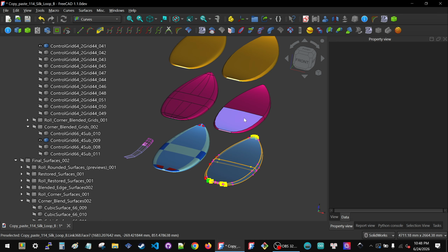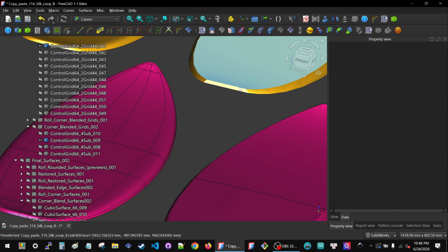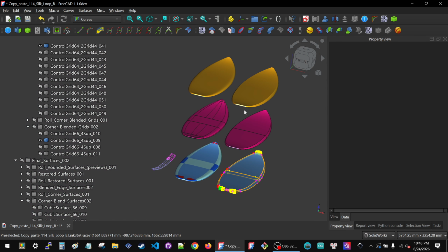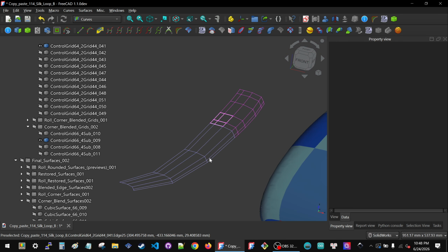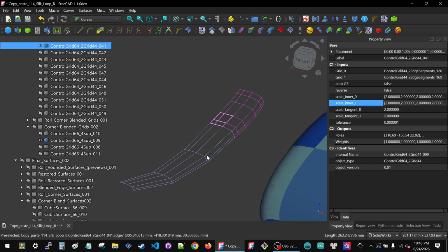If you have really crazy primary surfaces, stuff with belly buttons, like inverted corners, or you're blending a lot away, you might end up with grids that come with a weird S-curve. And you can use these values here to try to cancel out the S-curve and bring it back to a normal shape.